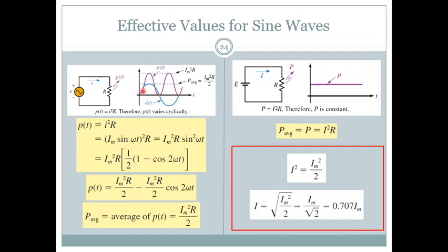This one period is in this case actually this one. You don't have to go for the full cycle of the input waveform or the current source, but this is actually a cycle for the power. You do that integration over a period, and that's because this is cos 2 omega t, so that is twice the frequency, right?